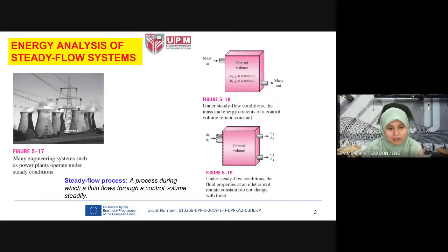So when we say steady flow process, it normally means that the mass, for example, is independent of the period of time. So if in your energy balance equation you have those parameters, mass, pressure, temperature, the differential of those parameters will be zero, because they do not depend on time, on the period of time of the process.